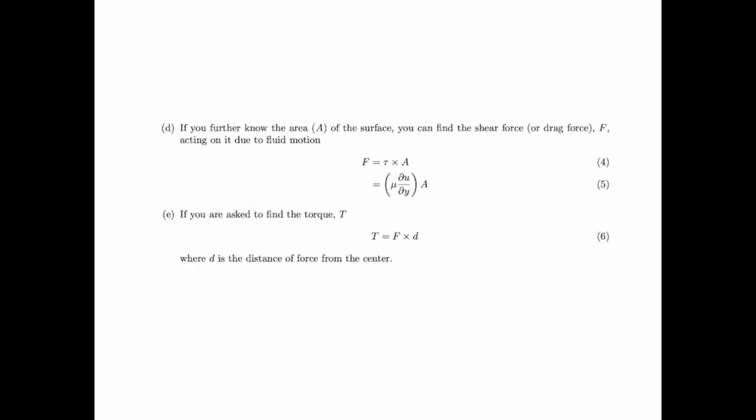Finally, if you know the stress, you can multiply by area to find the force. If you know the force, you can multiply by the distance or the radius to find the torque, right? So that goes through that problem again.